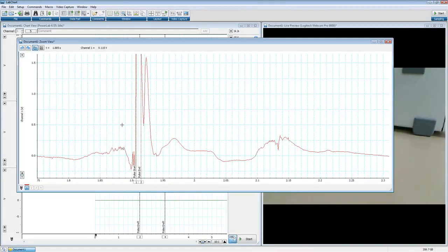It's basically a way to account for noise, and not to constantly have fast response output being triggered over and over again. It allows you to put a little buffer in. Once we trigger, it has to go below the trigger threshold by a certain amount before it will trigger again. And that's all the hysteresis value does.